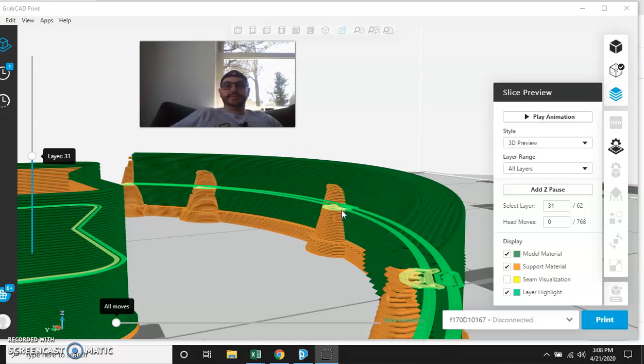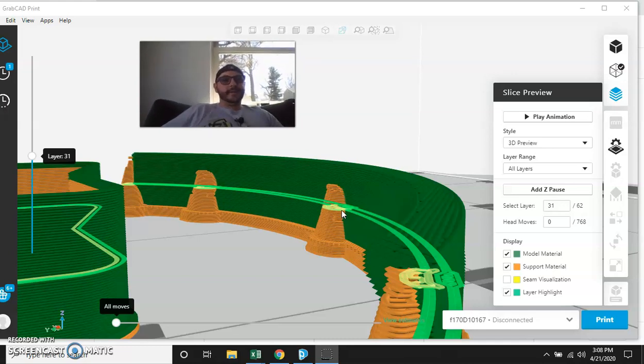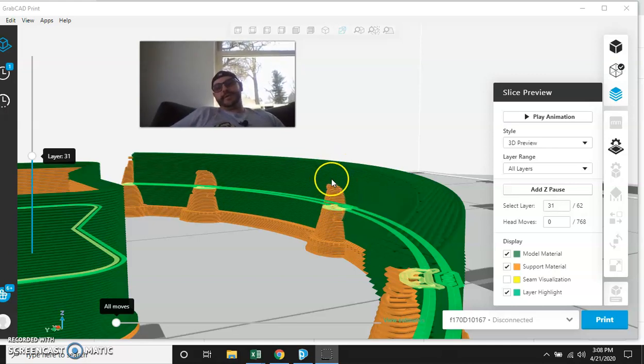And so it becomes an issue, and 3D additive manufacturing and 3D printing isn't as simple as everybody makes it out to be, because there's no way for us to get inside here without breaking away material, okay? No matter how I built this, because there is this inner piece that's carved out, I'm going to get support material inside and it may not function. But this design may work on other 3D printers. That's just some of the issues that we run into.